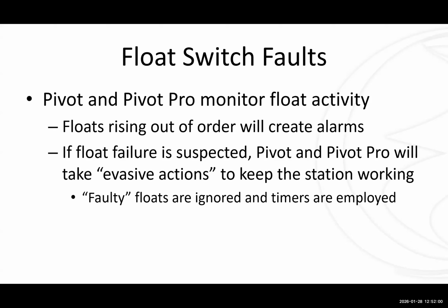So it's calling attention to it, but at the same time, it's working to keep your system at an operational level. If the high water float comes up and the two lower floats don't come up, it makes the same kind of assessment that something must be stuck or there's something impeding those floats' operation. It'll start the pump, or pumps plural if it's a duplex system.